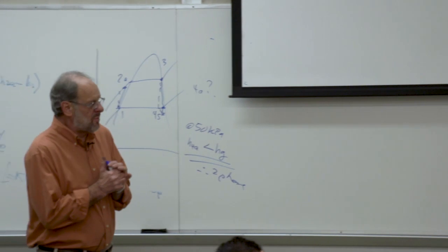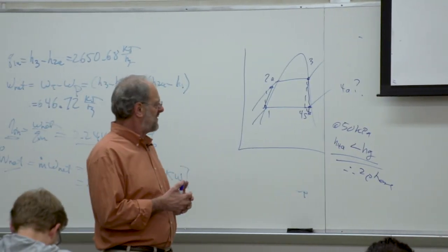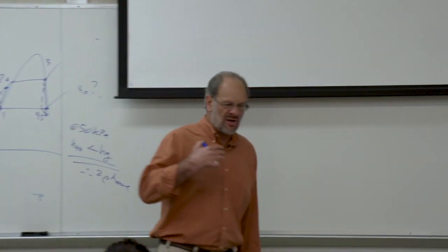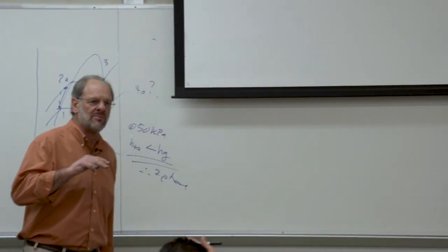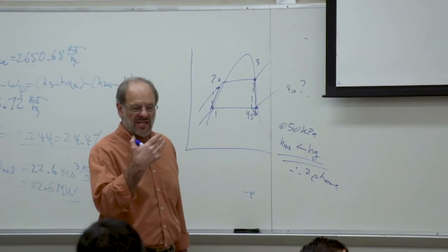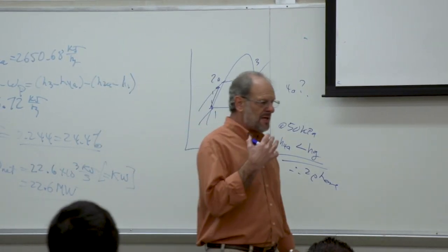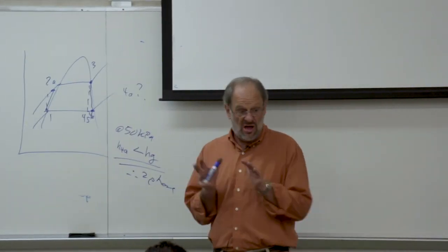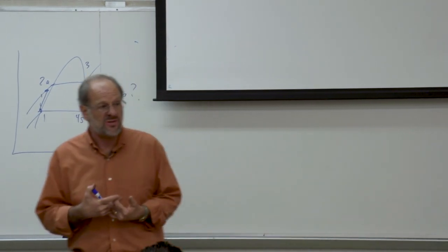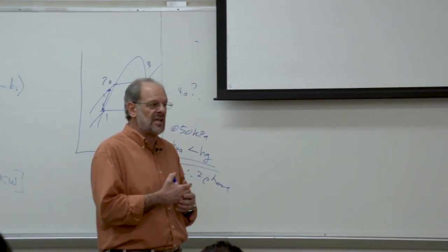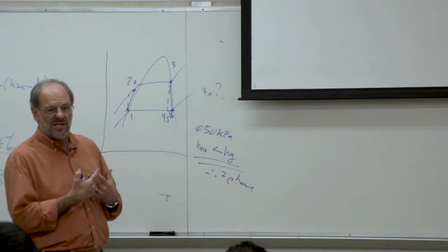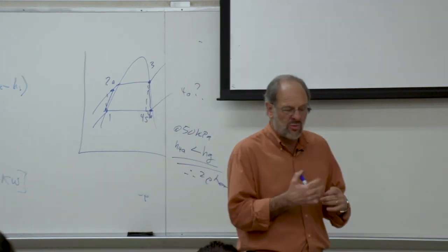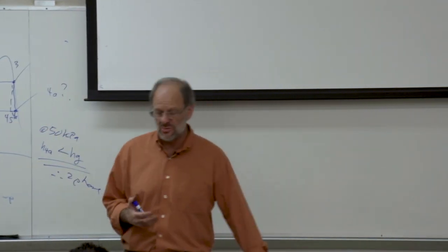Okay, so what could we possibly do to improve the thermodynamic efficiency of a Rankine cycle? One thing that we can do is regeneration, but I mentioned previously that we have a little bit of a problem with regeneration, at least in the same context as regeneration in the Brayton cycle. Keep in mind that in the Brayton cycle, the discharge from our turbine was always at a relatively high temperature, several hundred degrees, certainly well above the ambient air temperature, and even well above the temperature of the ambient air that's compressed from point 1 to point 2.